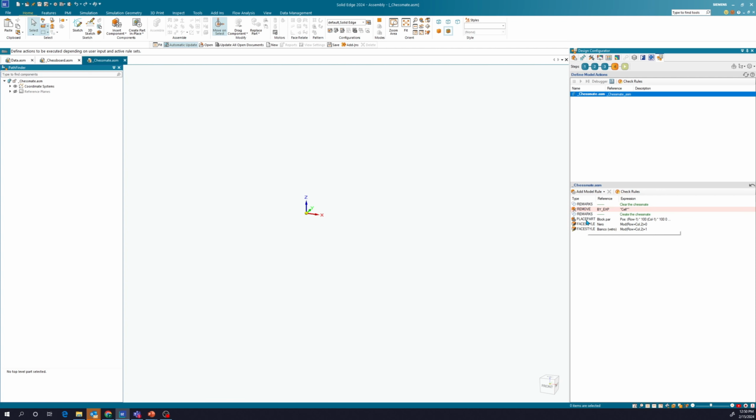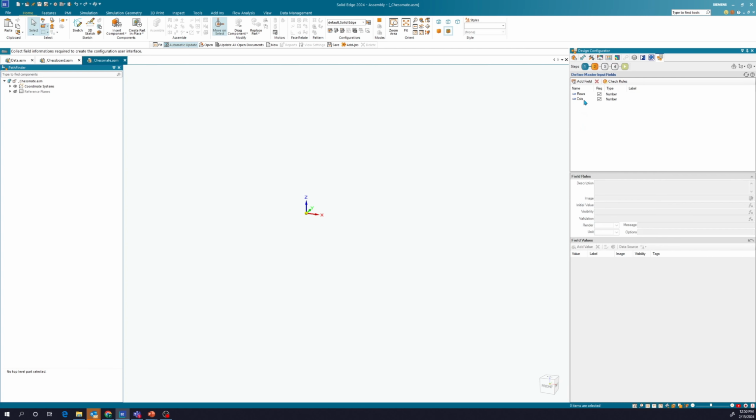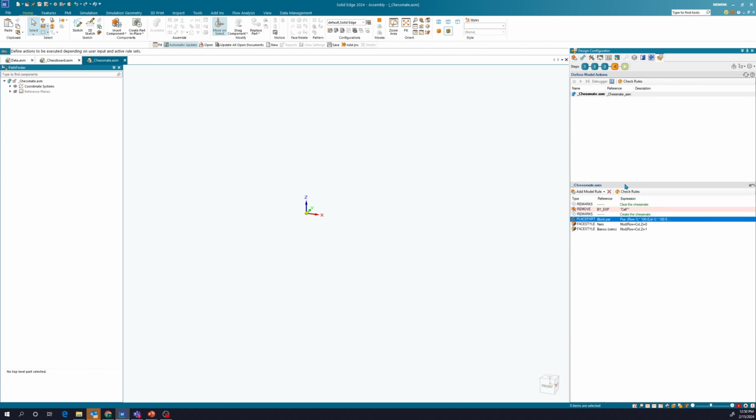So I want this place part and specific set of face style in the way this is defined to run each time I select my 2 inputs, and the 2 inputs are going to be rows and columns. So I'll go back to step number 4 and add those for each loops. Go to workflow, specify for each loop.